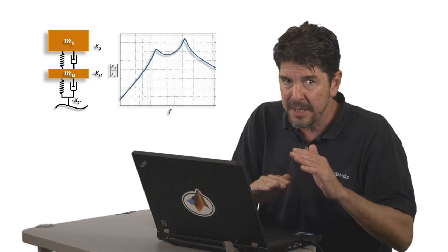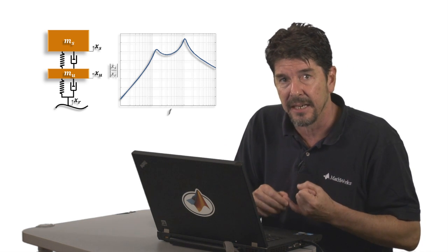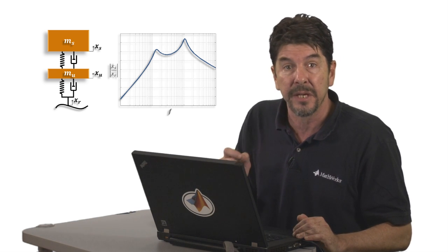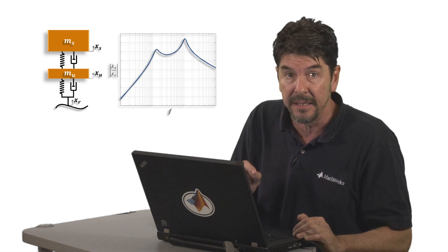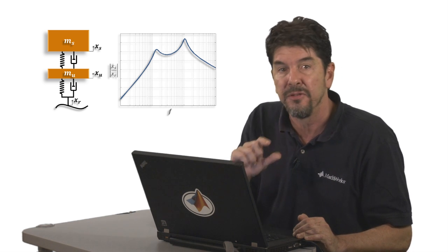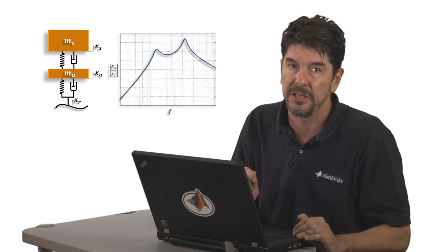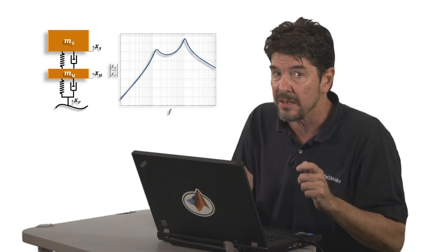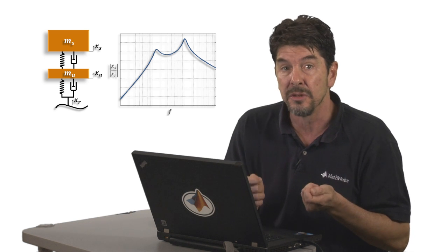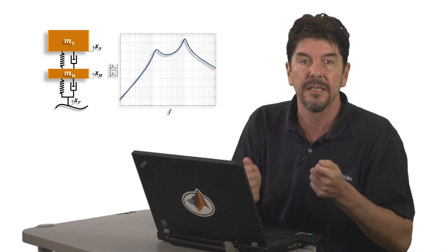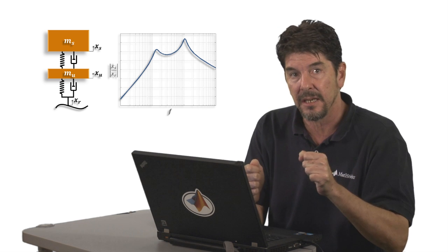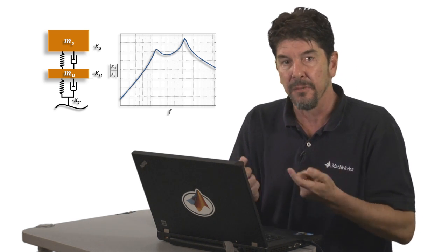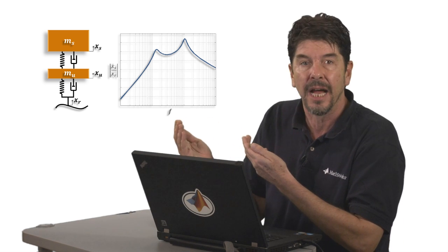By the way, the bumps under the car don't need to be really big. The critical factor here is the frequency of the excitations. If you hit that rumble strip at the right speed, those tiny bumps can produce very large vertical acceleration jolts on the chassis. And even though those strips are designed to make you instinctively slow down, sometimes as you take your foot off the gas, you can feel the shaking become even worse before it starts to get better. That is probably because as the car slows down, the frequency of the excitation also goes down.